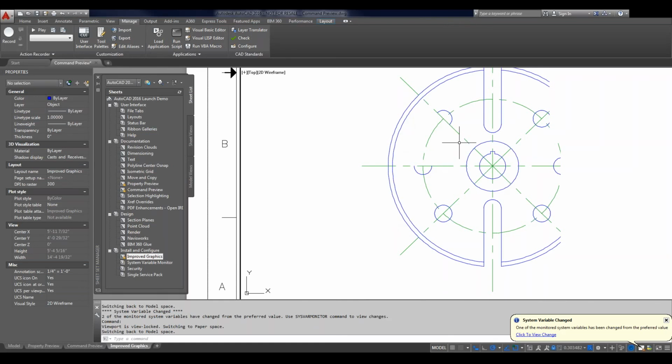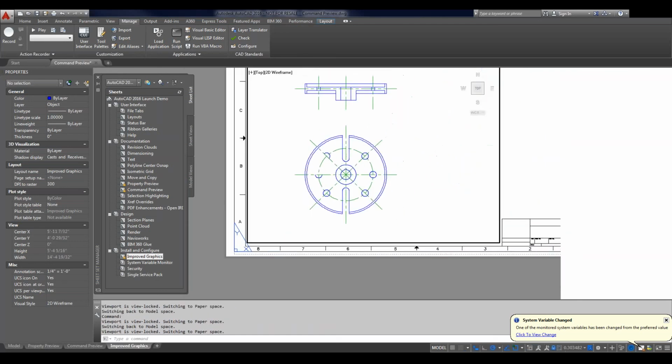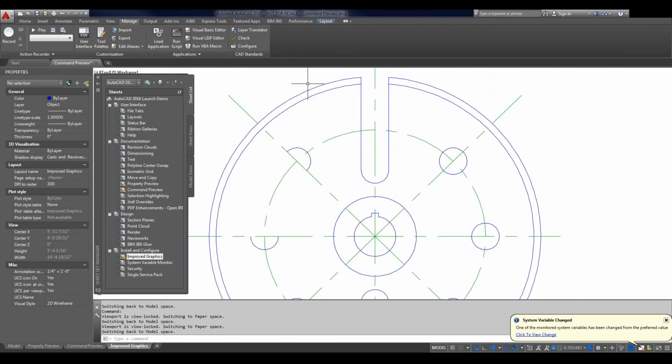So nobody really noticed the jagged lines, did they? All right, so notice the circle, the curve is not very smooth. And that's because I have my new system variable, HQGeom, turned off. And again, I do need DirectX 11 for this to be enabled.